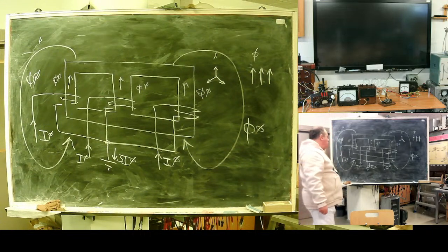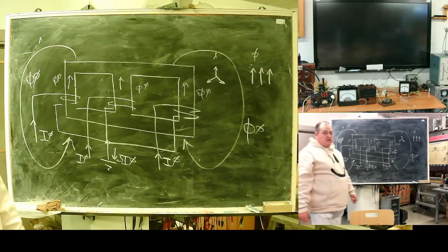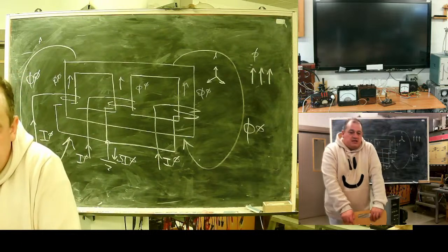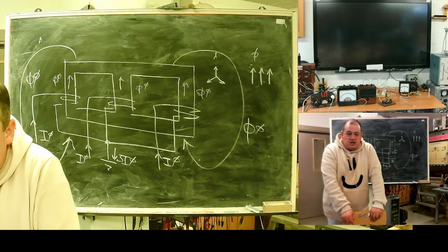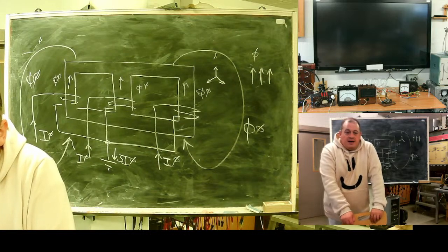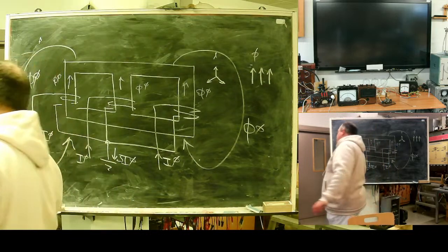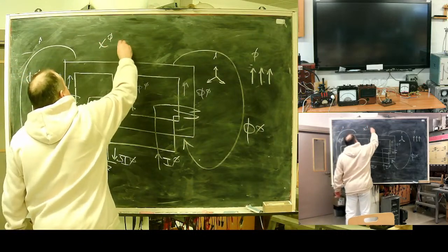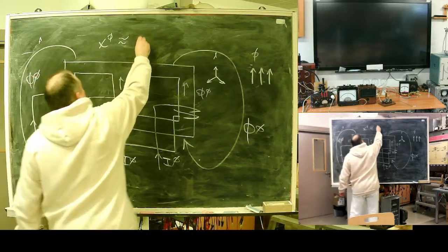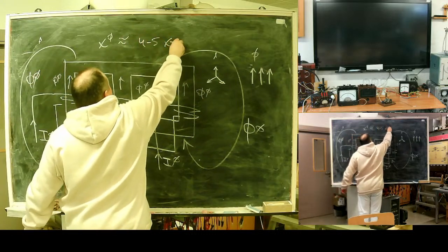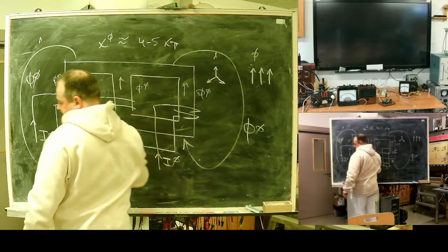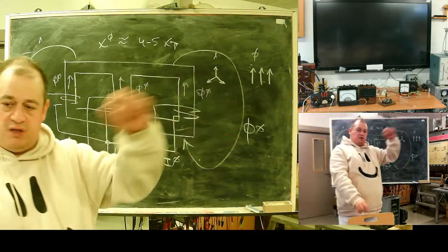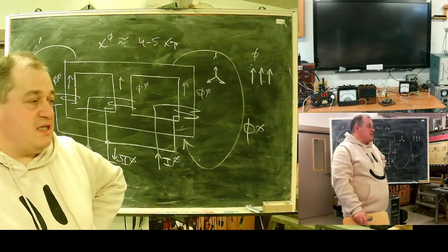No, it's not true. The transformer has its vessel, some kind of shrouds, some support constructions around. Really, it will have a zero sequence reactance of approximately 4-5 times the transformer's. Not infinity, higher in the longitudinal direction, but you will get something.